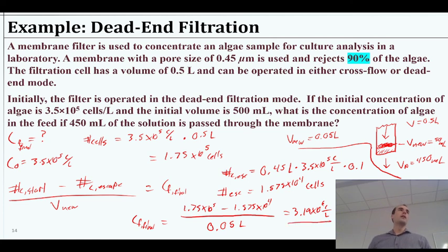So that would be our answer then. Does that make sense? You see now how it really was sort of just mass balance. Filtration stuff was just added context. So we'll get in next time to more of how does the pressure affect the permeate, and how does that fouling resistance work, some things like that to give us some more equations. But I wanted to start here because I want to make sure that you're recognizing that the basis of this is just the same principles of conservation of mass or number that we've been dealing with, right? So try not to overthink it.